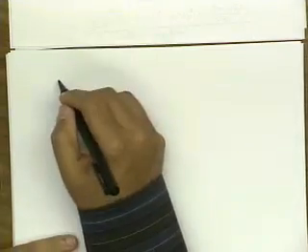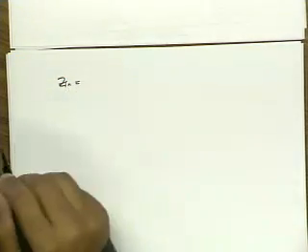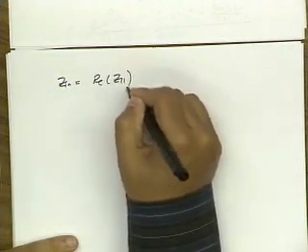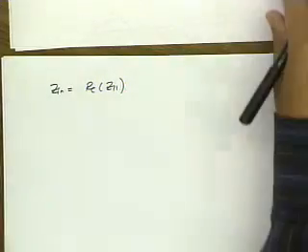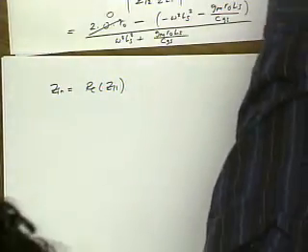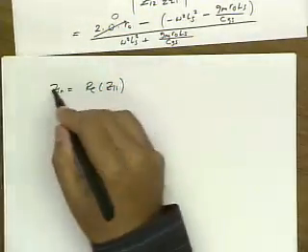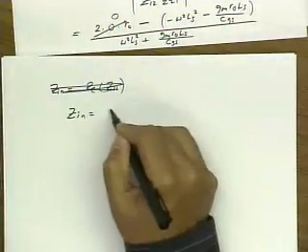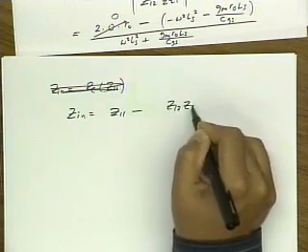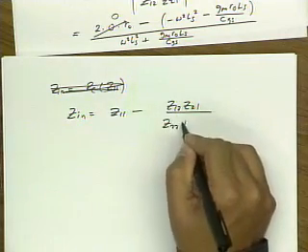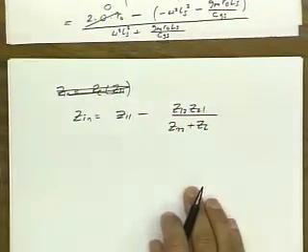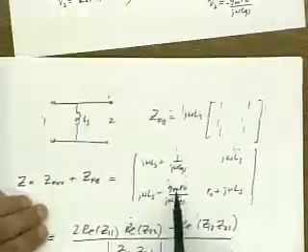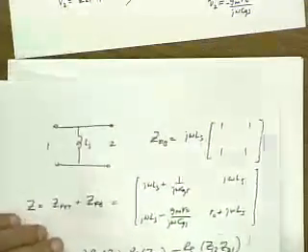All right, so let's show that this in fact is equal to the source resistance. Let me look at Z in. So Z in is the real part of Z11, right? And again, if I go back and look at my Z matrix, sorry, what am I saying? Z in is Z11 minus Z12 Z21 divided by Z22 plus ZL. Okay, so now if I go back and look at this matrix, I can just substitute here.